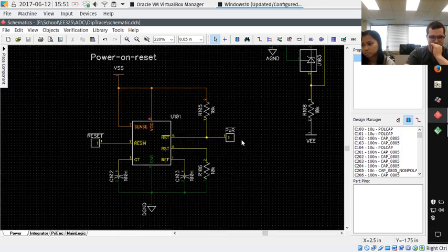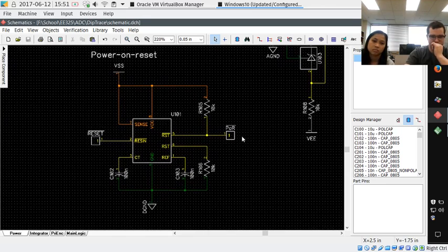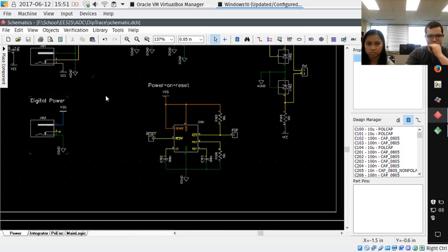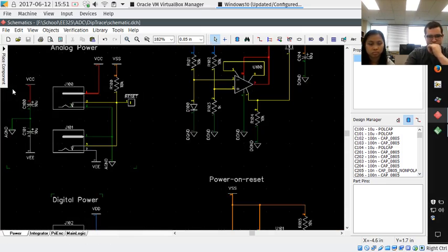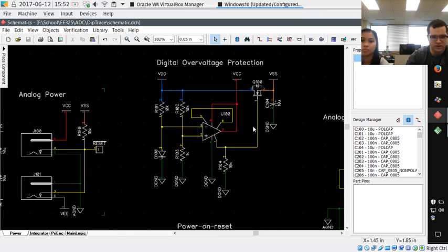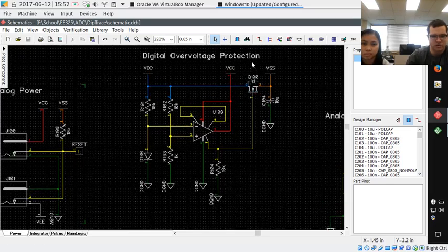It's mainly a precaution, especially for initial turn on when we don't necessarily know the states of flip-flops and such. So you can see here, these are the power jacks, and there's some decoupling around it. But these here are switches inside the power jacks that are often used to switch between battery and supply, but in our case we're using them to switch the digital circuit enabled and disabled.